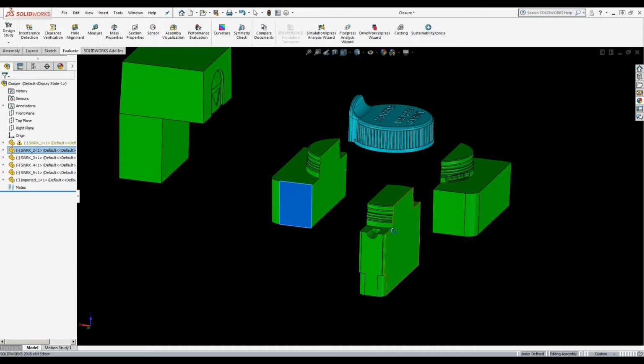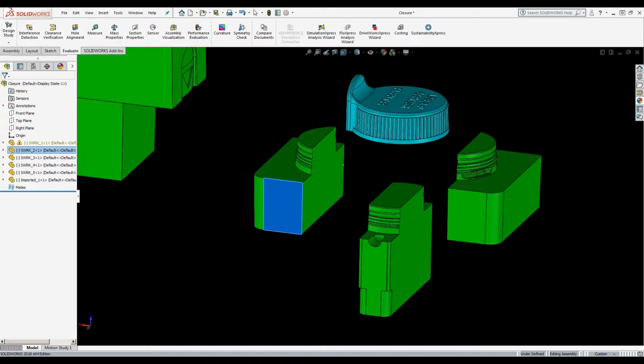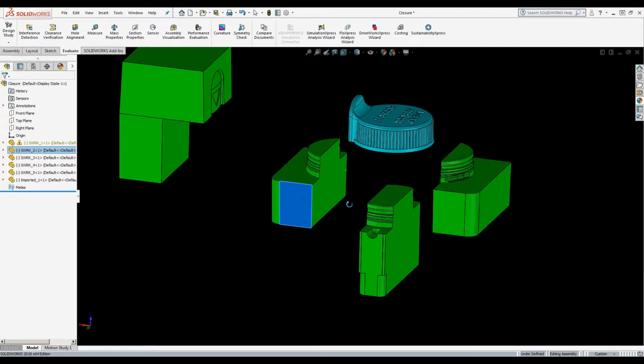Okay, are there any questions with regard to this part? Okay, we do have a couple questions. Could the operator remove two pieces be automated, or did that have to be a manual process? In a production environment, it could be automated. Potentially, it could be automated with some sort of collapsible core. Obviously, much more intricate, detailed, and expensive tooling.